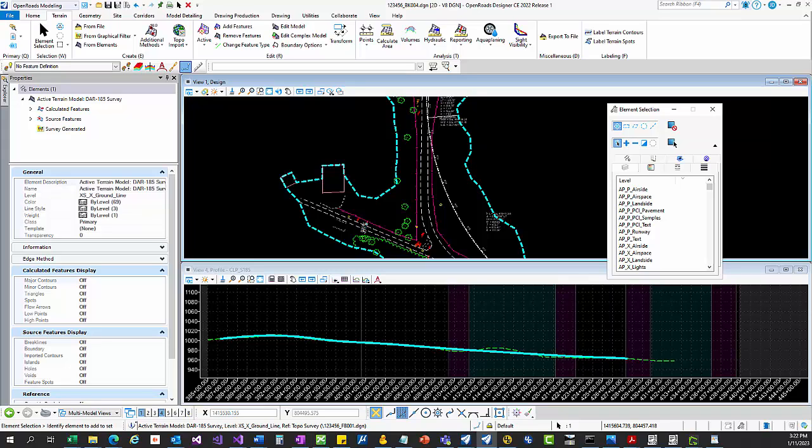In this video, I'm going to show how to export surfaces to a LandXML file. Your existing surface needs to be exported to LandXML file and submitted with the project, and will be made available as a reference only for the contractor. If you happen to make any proposed services, those should be exported to LandXML as well.